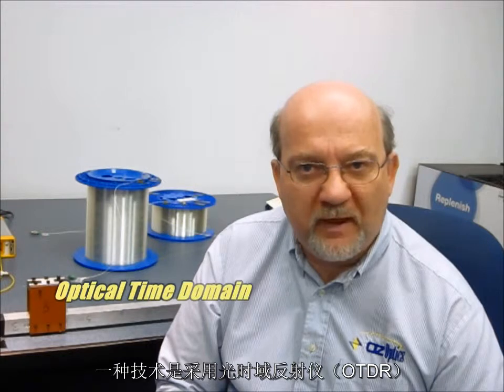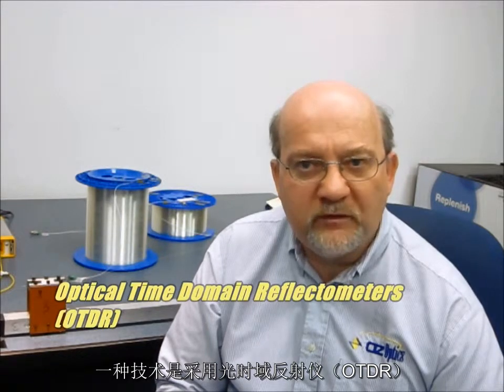One approach uses what are known as optical time domain reflectometers, or OTDRs, to monitor fibers. These instruments send optical pulses through a fiber and listen for echoes. If the fiber is bent sharply by a tree or branch, either a strong echo occurs, or echoes farther along the optical fiber get weakened or attenuated. However, it takes quite a strong bend to cause even a small change in these echoes.